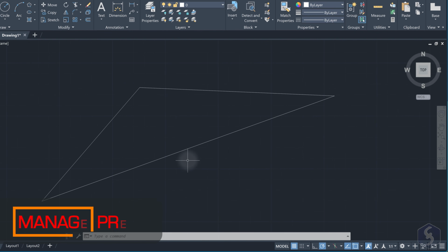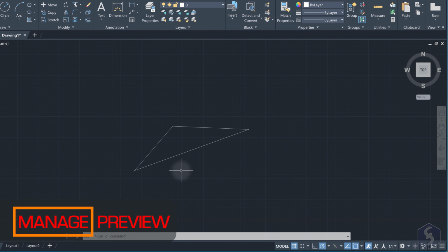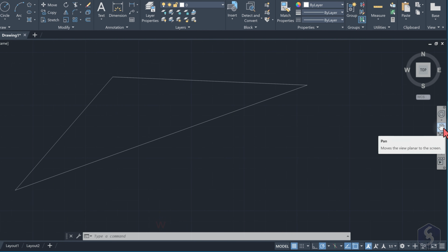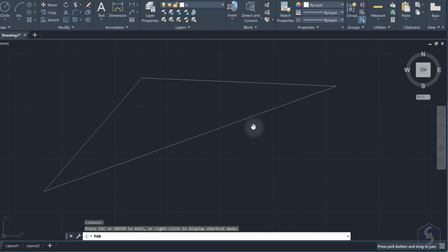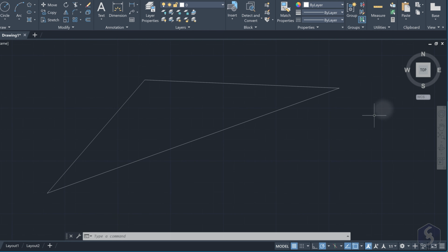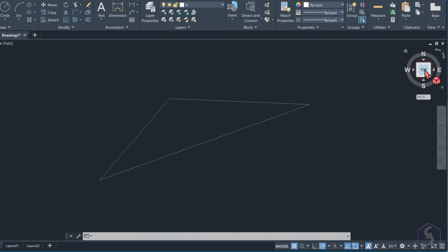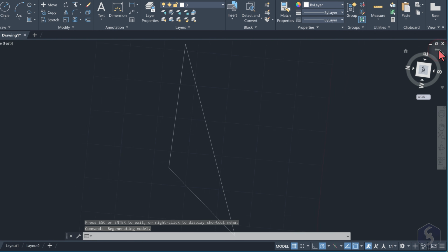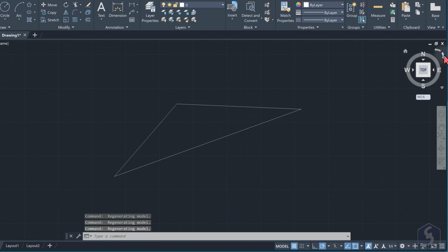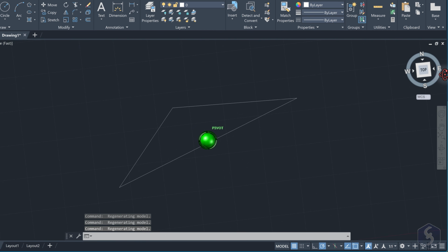To check your drawings, use the mouse wheel to zoom in and out. On the right, enable Pan to click and move the preview, using the Escape key to exit. In the top right corner, you get the 3D View cube, setting the project perspective. In 2D projects, this is showing top, such as a top-to-bottom 2D perspective. Use the arrows to rotate by 90 degrees or drag from the circumference to rotate in 2D.